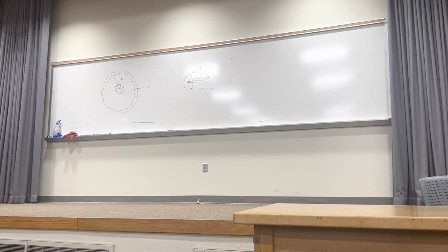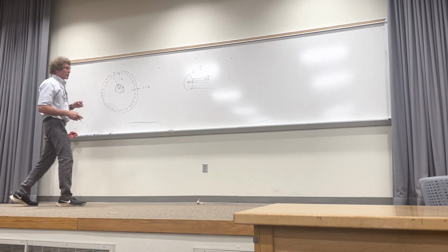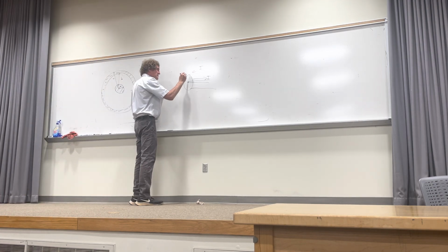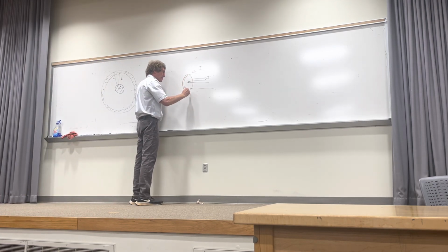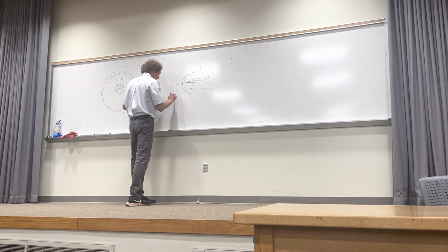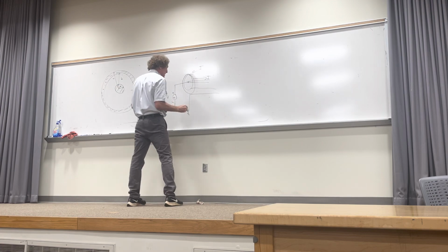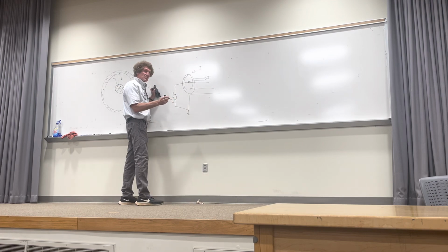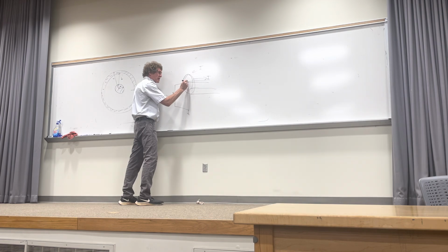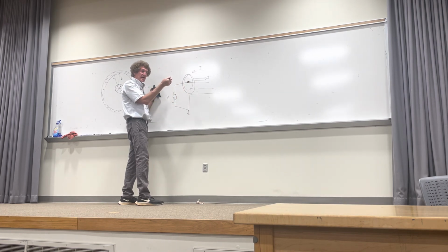Y'all follow me? Now here's the thing that's important. When you have a coax cable like this, even though this has some thickness, and you drive it with a time varying voltage signal, I'll ground that, and I'll also take it connected here. We'll assume this thing's long. The actual electric field will be set up so it'll hug the surface of the inner wire, so you'll go one skin depth into that surface.